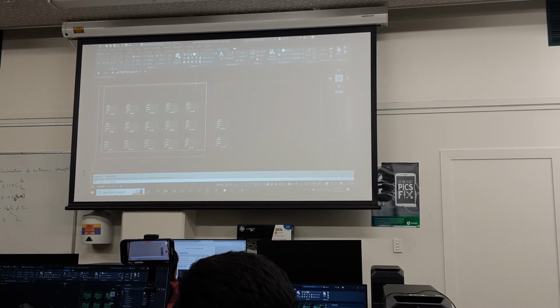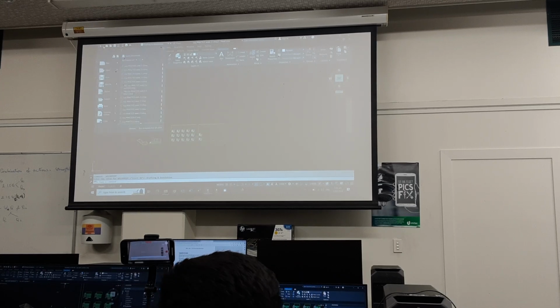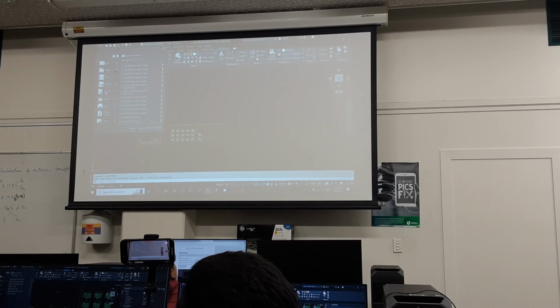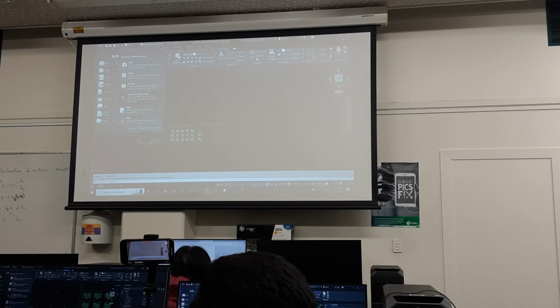So what we do is we come up the top here, by the C up there, we come down to Export and we go across to Export Civil 3D Drawing. Now, you can export DWFs, which will go into AutoCAD as well, and you can export PDFs, which you can put into documents.